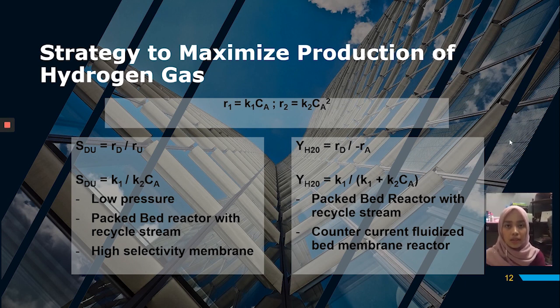According to Lee, certain membranes that have perfect selectivity to hydrogen, such as dense Pd-based membranes, are used to obtain a very high purity percentage of hydrogen, which doesn't require additional purification methods such as the ones in the conventional process.